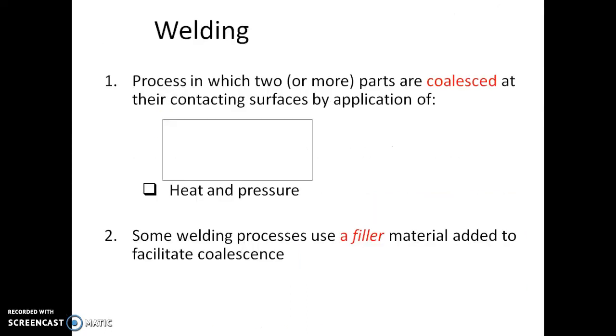What exactly is welding? It is the application of heat so that two metal parts get fused. There may also be application of heat and pressure at the same time. In some cases only application of heat is sufficient; those are called fusion welding, whereas in some cases both heat and pressure are applied; those are called solid state welding. Again, filler material may or may not be used.